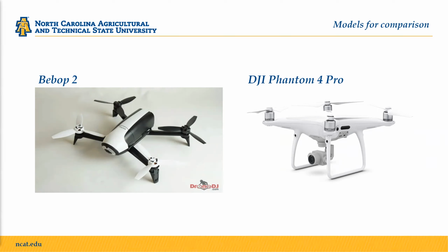The Parrot Bebop 2 uses a P7 dual-core CPU, a quad-core GPU, and 8 gigabytes of memory, and the operating system is a stripped-down version of Unix referred to also as BusyBox. The software surveying the vulnerabilities found in Phantom and Bebop drones, including drone hacks based on unprotected Wi-Fi, access to drone configuration files, and changes to settings in flight and GPS attacks. Wi-Fi insecurity, the Parrot drones allow multiple connections through Wi-Fi, which allows an attacker to tamper with the system and hack the drone.